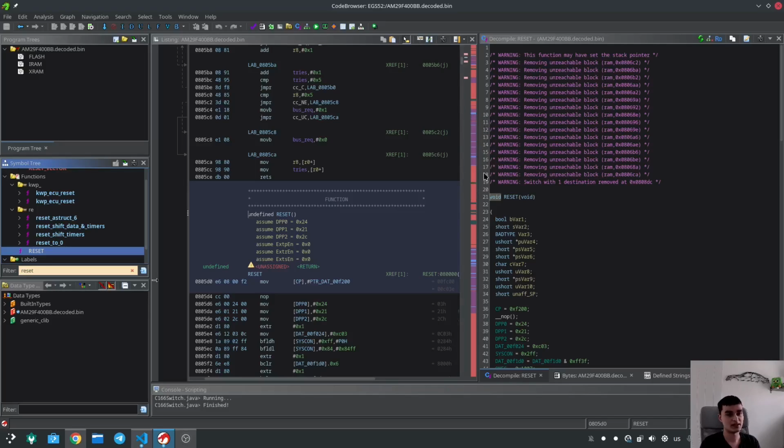This here is the Siemens application layer, and I found that this section is in control of all of the inputs and outputs on the TCU. It's involved in reading and writing to CAN bus, and also the operating system itself, because it is a multi-threaded environment, all the code for that is here.